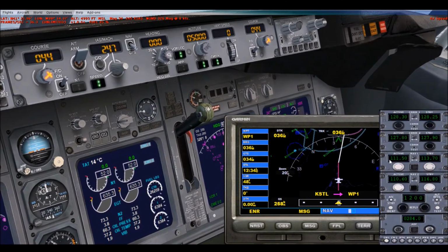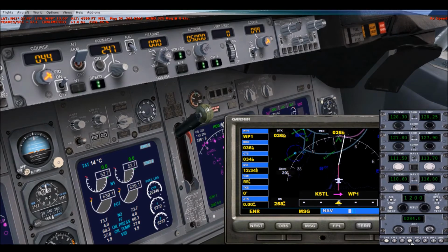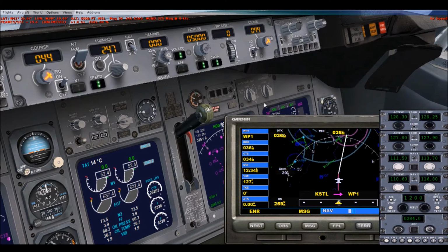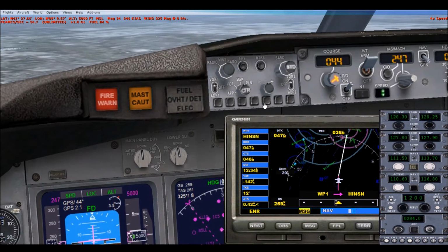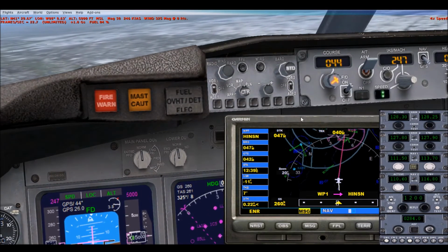So we are going to hit this button, and it becomes active. As you can see, this light pops up. The nav1 light pops up. Once we hear the beep, we know we've entered that frequency. As well, you will see the letters ID spring to life right here. Once we see that, and once we hear that code, we're in business, because that means we've locked into the runway frequency. Oh, there it is. ID popped up. We'll hear the code. There it is.